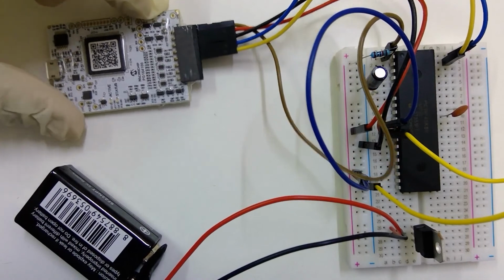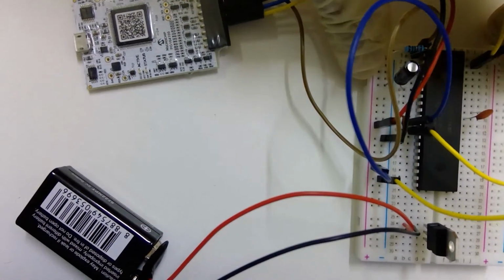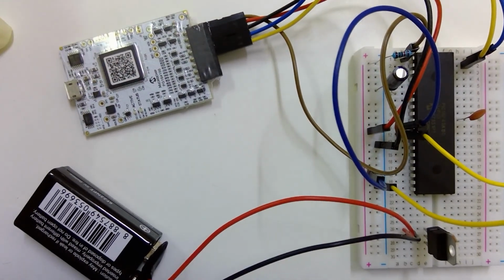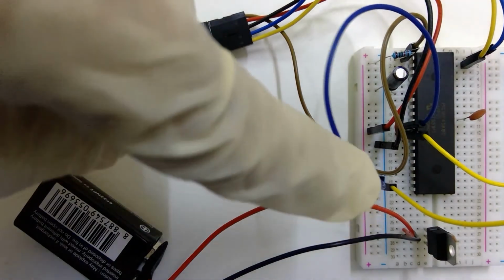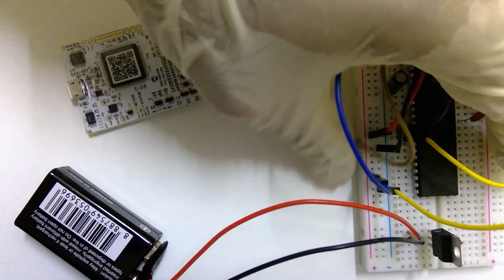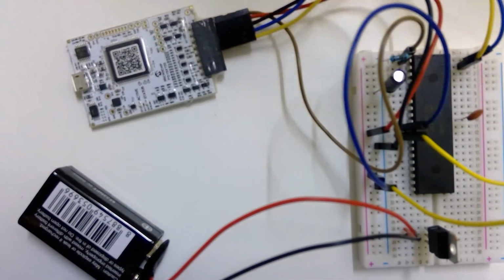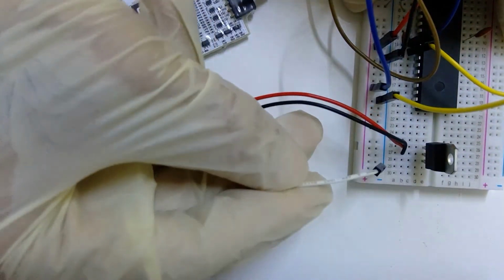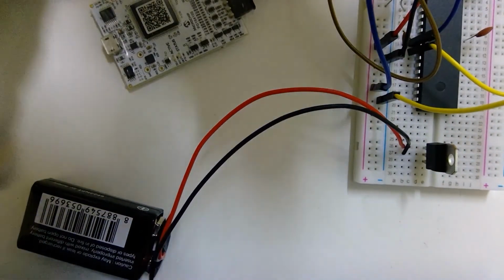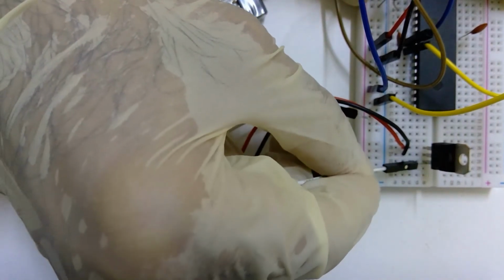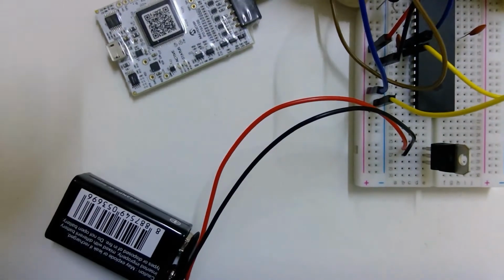Now before connecting Mplab Snap with the PC, let us power up the microcontroller first. So if you have a multimeter, before you connect the microcontroller, make sure that you get 5 volt on the output pin of the voltage regulator. So using a multimeter, just check whether you have 5 volt on this pin of the voltage regulator.